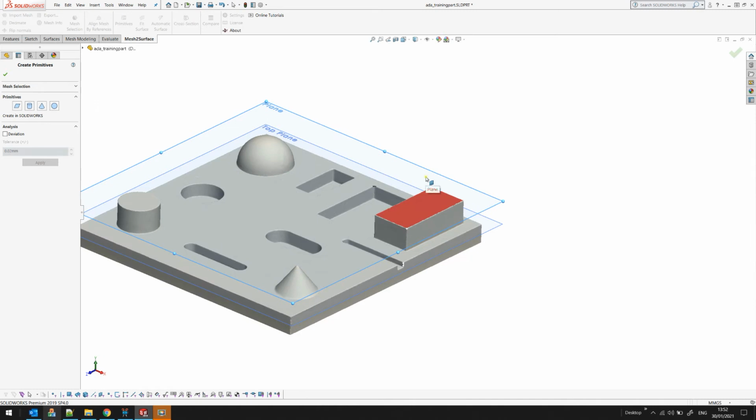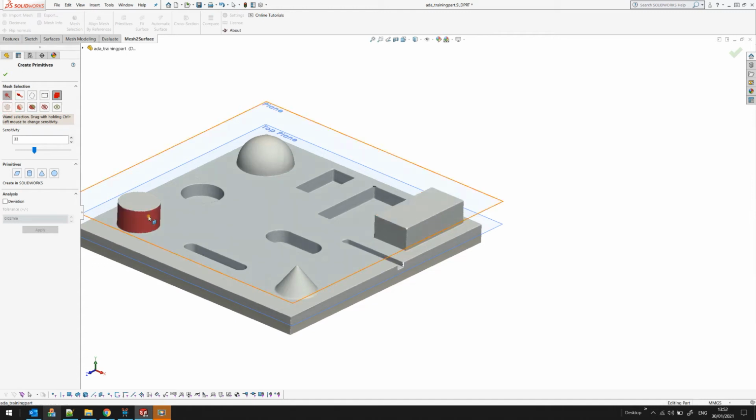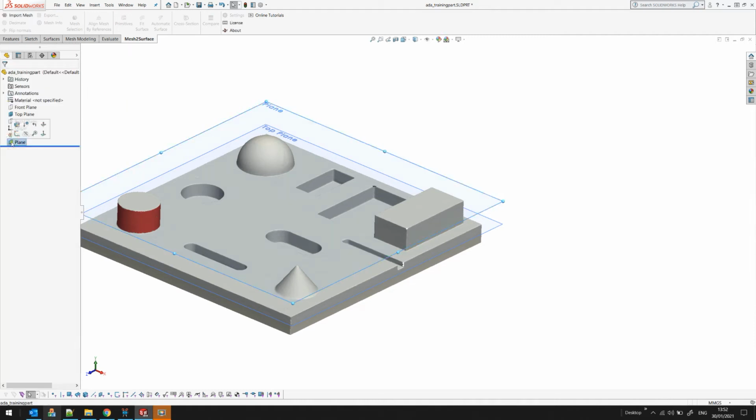Why? Because when we want to create alignment or we quickly want to extract a lot of reference geometry, it's good if we still stay here. For example, I can just come and unselect and take my cylinder here. I can fit a cylinder, extract, etc. But I will just press OK now and see what happens with this plane.